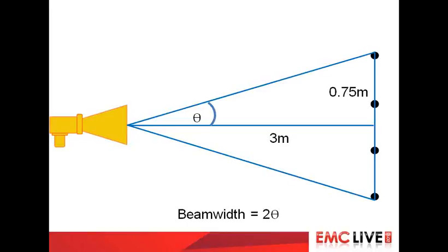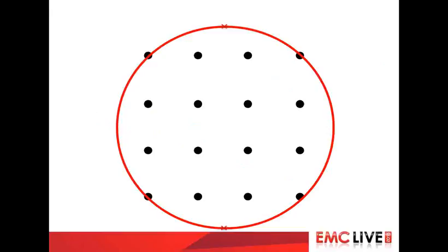But it's a bit of a trick. You have to be wary. Antennas don't give off square radiation patterns, square section radiator patterns. They're going to be round or somewhat elliptical. And so it's easy to be fooled to think you just take between the two vertical extremes of the measurement points there. In actual fact, you have a circle, as you can see. More likely an ellipse, but for our purposes, let's go with a circle.